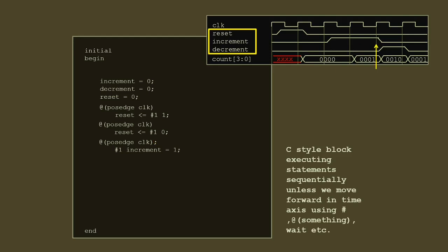So one way is that I write @(posedge clock); twice. But normally, if I want to spend multiple clock cycles, I use this loop. This is also another neat loop. Repeat 2 means repeat twice. @(posedge clock) means